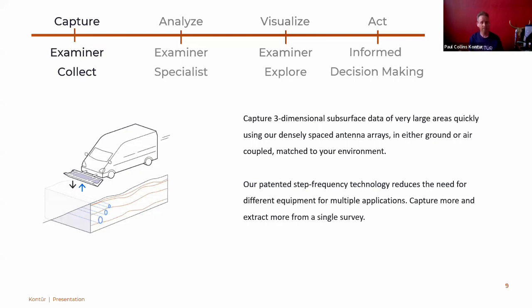If it's high speed, then air launched is your choice. Of course, it's going to be a little bit shallower in terms of depth prospection, but this isn't typically a pavement mapping device. And then with ground coupled, a little bit slower, but very useful for bridge decks, utility mapping, void detection, these kinds of applications.